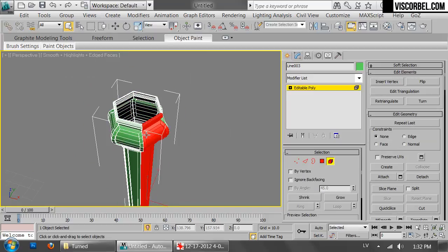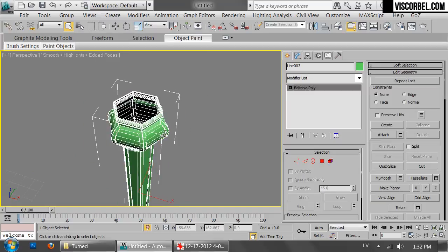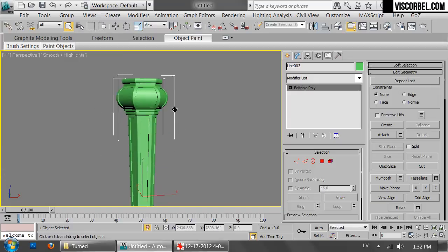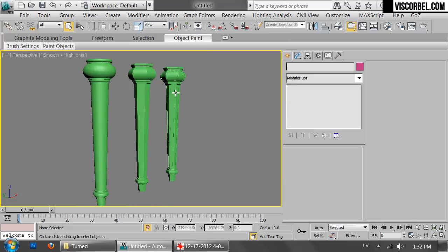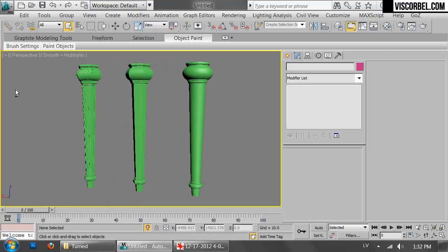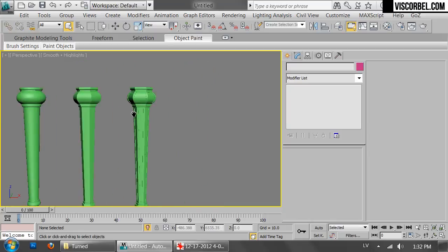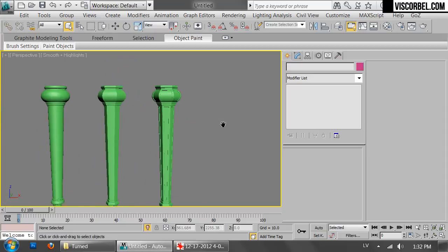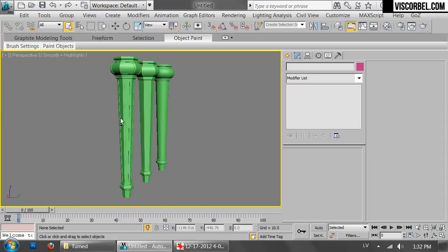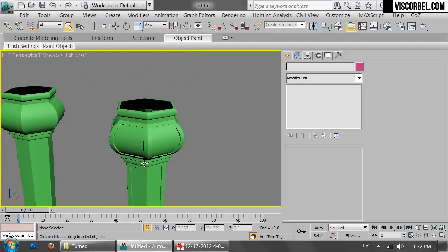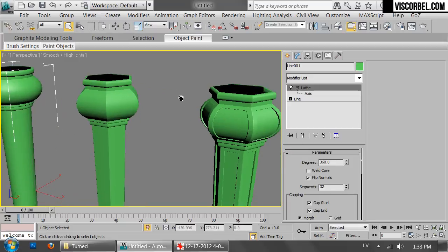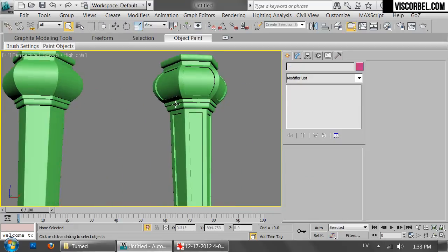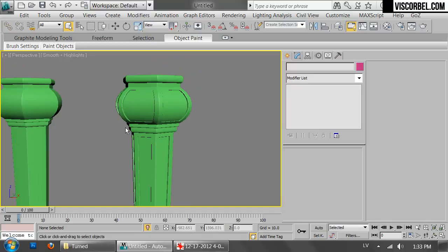And now when you select elements, it's one element. There are no seams, no splits. All right. And that's a simple but useful technique to use on segmented turnings that you need to adjust multiple parts of simultaneously. It gets really helpful when you have more pieces than 6. For example, you have almost round with 60 pieces and you need to adjust just one slice or 2 slices of that, and you can do that. You just have to calculate how many copies to use with the array tool.